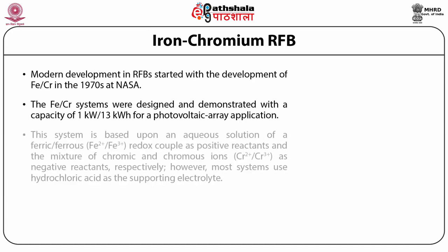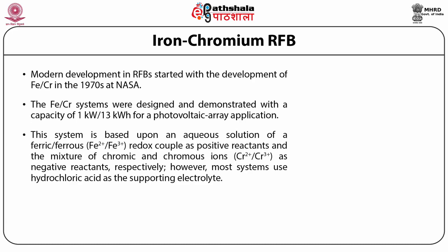application. This system is based upon an aqueous solution of a ferric or ferrous, that is Fe3+ or Fe2+, redox couple as positive reactants, and the mixture of chromic and chromous ions, or Cr3+ or Cr2+, as negative reactants respectively. However, most systems use hydrochloric acid as the supporting electrolyte.